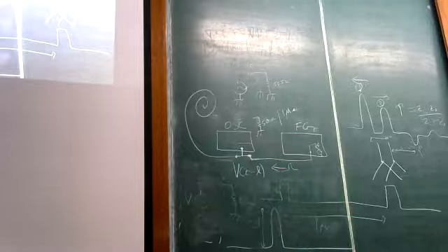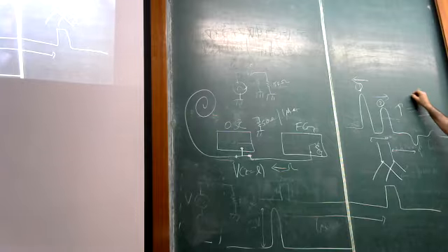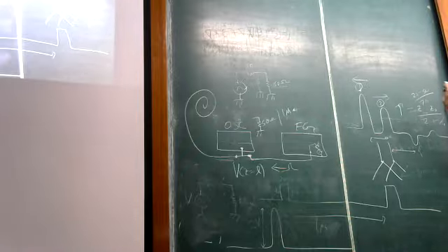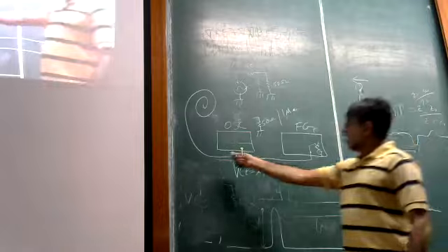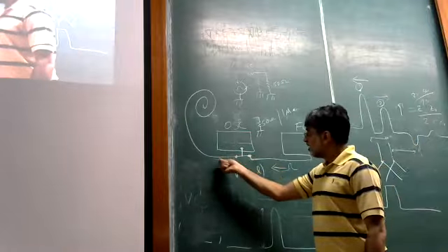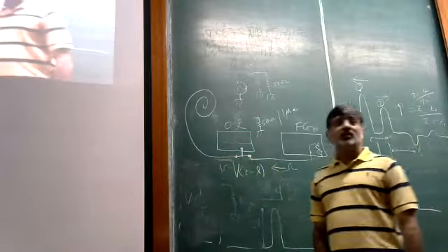The reflection coefficient is not -1, but it's minus something which is a number smaller than 1. In fact, it's going to be exactly 25 minus 50 over 75. So it's the same fraction, but now the sign is opposite, because the pulse which came back reflected with a negative sign.